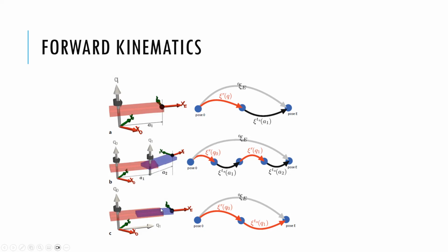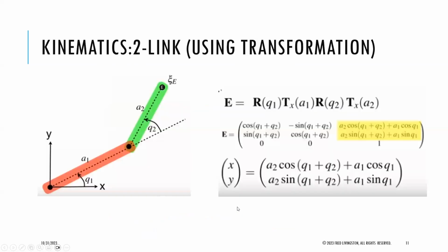And this one here is a rotation prismatic, so this is the RP example. We have a rotation and a prismatic link, and I have a rotation component and a translation component. And I've done the pose for that. So doing the kinematic chain, there's a rotation, translation, rotation, translation. And I did the math there. I get a matrix representing the XY location and the orientation of that. And this is a 2D example, so it's a 3x3, and a 3D example will be a 4x4 matrix.